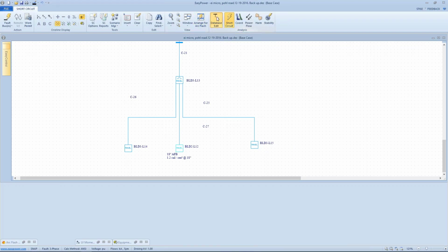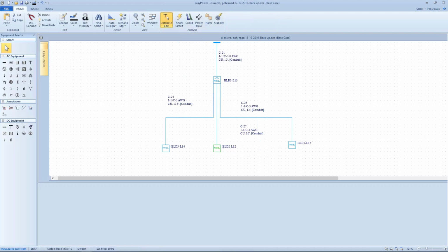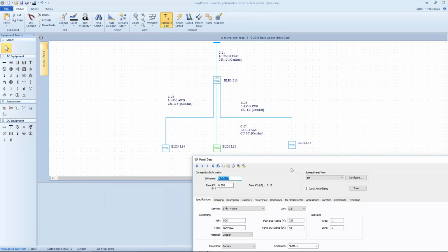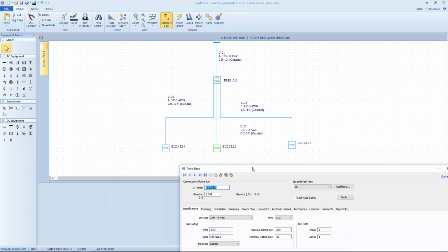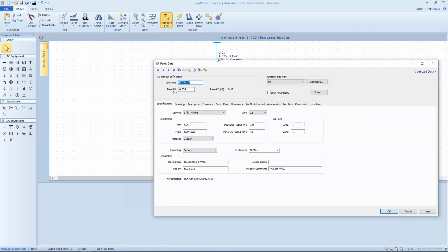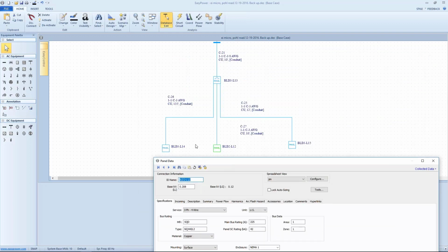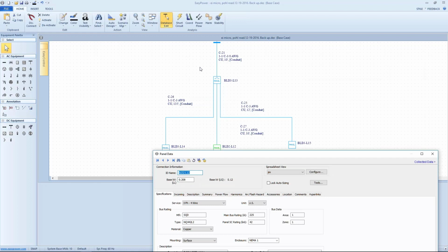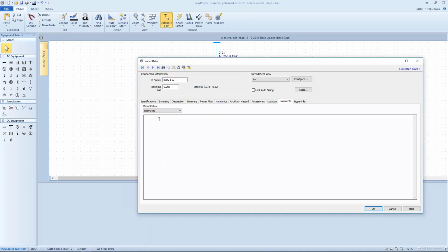Now, what's the trade-off in doing that? Well, first of all, let's go back to I've done this based upon company policy and the assessment that these current levels and voltages and air gap involved are well within the boundaries of the recommendation in IEEE 1584 that this is a negligible arc flash hazard. What I would like to do is make a notation to myself, and I might say something like arc flash hazard minimal based on IEEE 1584.